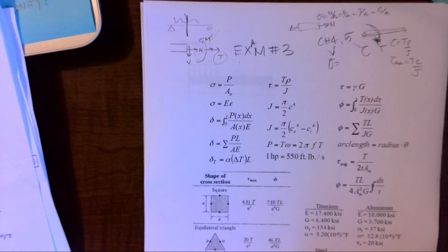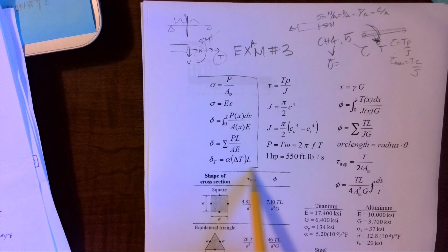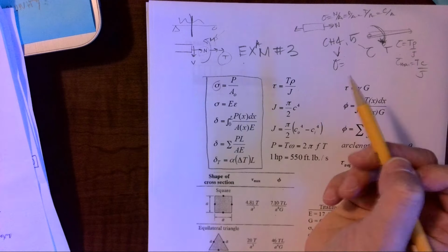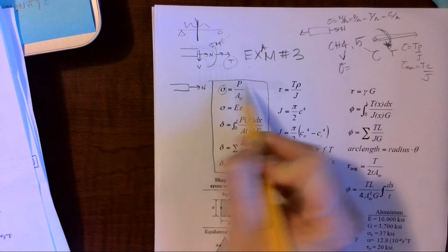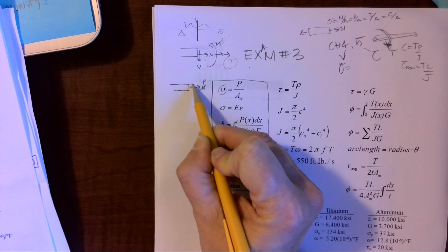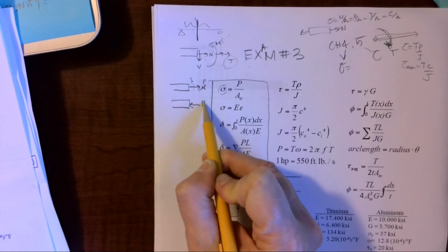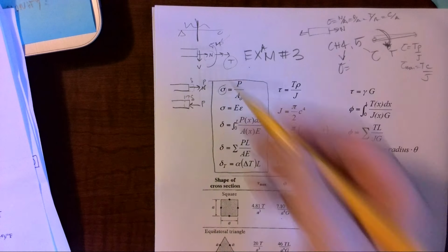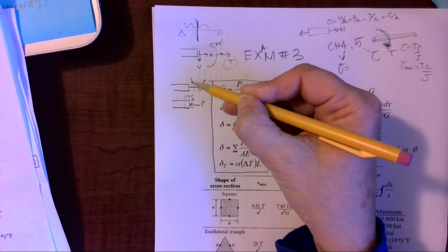Okay. So looking at this equation sheet, I need to be able to distinguish as a student what it is I'm looking at. And I'm going to look right here first. This is normal stress. You need to remember that sigma means normal. I have a normal force, or we could call it P. It is going to cause elongation, and I'll have a delta. Again, we have force P, and this time we have compression, negative delta. So this would be a negative P, positive P, negative delta, positive delta.